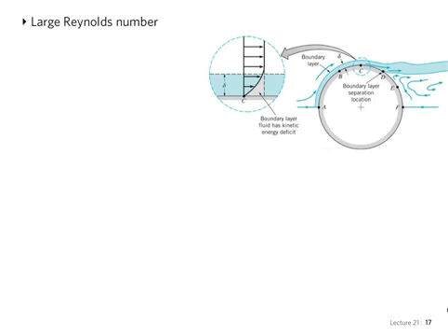So if we add some viscosity, then the pressure distribution that we had from the inviscid case transfers over to this case without any changes, because of the same argument that we made during the boundary layer discussion. So the pressure distribution of the inviscid flow around the object is imposed now on the viscous flow inside the boundary layer. The only difference is that we have the no-slip boundary condition. So the flow in the boundary layer must adapt, changing rapidly from a given free stream value to 0 through this velocity gradient.